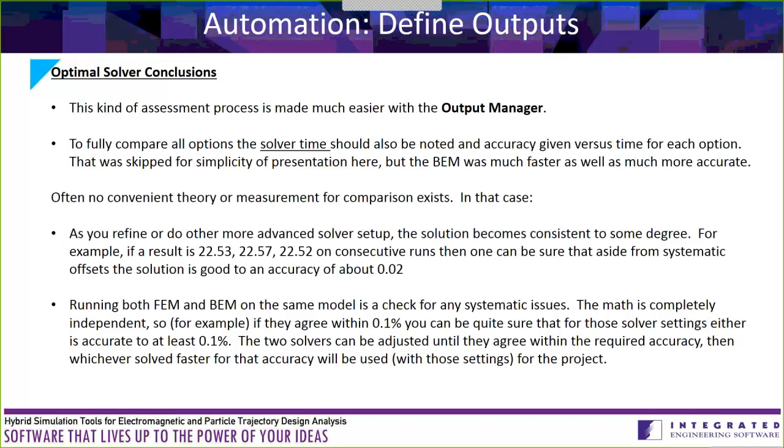So for this particular type of study, just a piece of advice, what you really want to do is to compare solver time. You don't want to just look at settings, because for all you know, my best case took a lot longer than my poorer case. So it's really solver time you want to be focusing on.